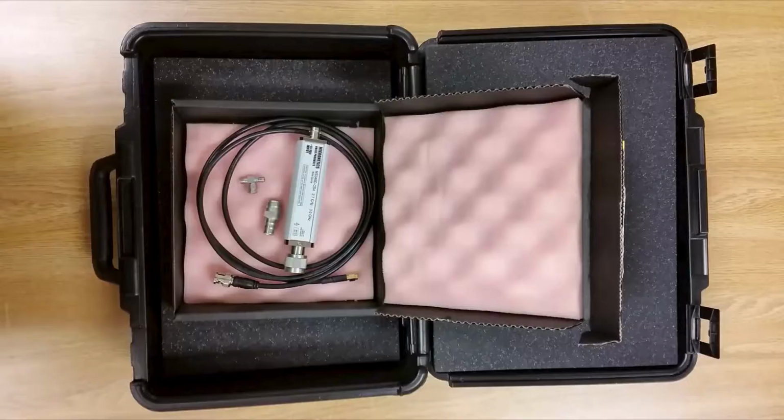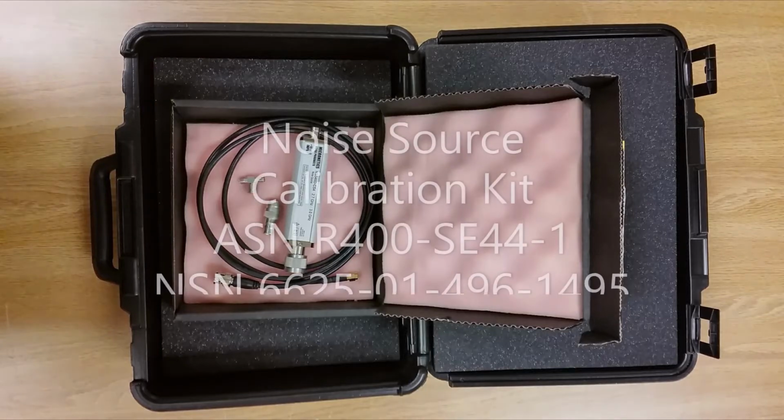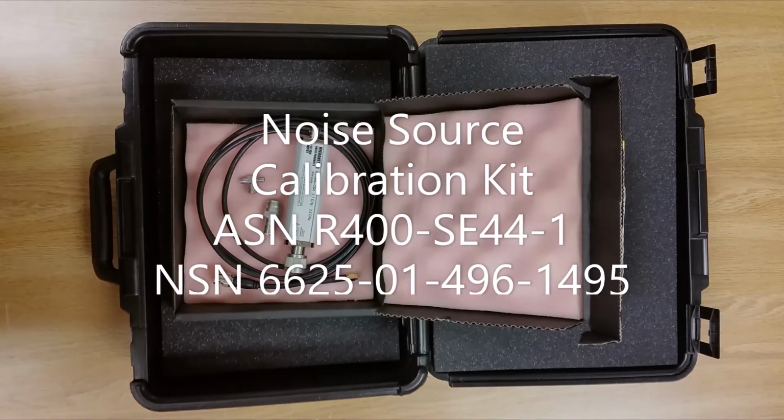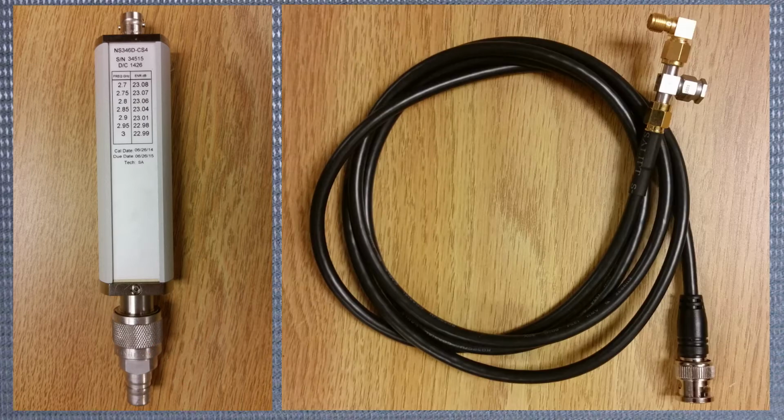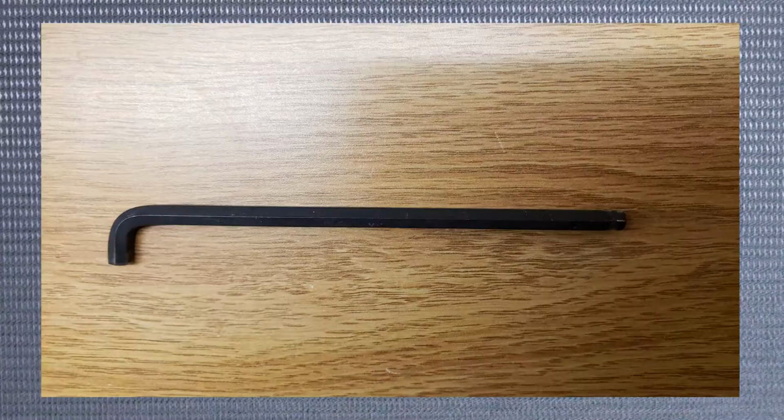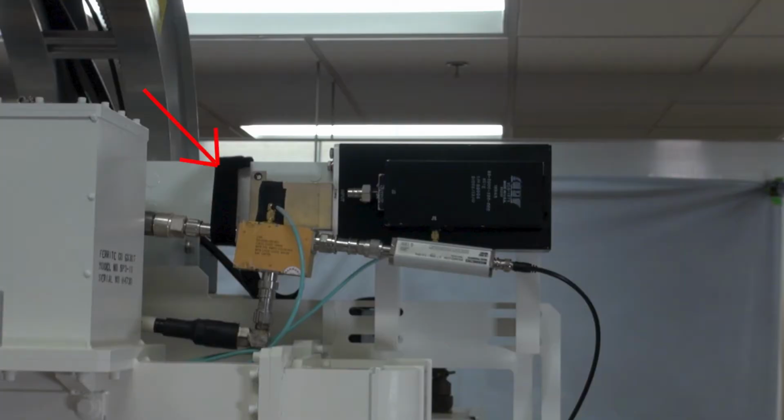This procedure requires you to pre-order from Shared Support Equipment Noise Source Calibration Kit ASN R400 SE44-1, which contains a Micronetics noise source, type N female to QN female adapter, BNC male to SMA male cable, SMAT adapter, and an SMA right angle adapter. You will also need an SMA torque wrench, 3/16 Allen wrench, and tie wraps or Velcro cable tie to secure the LNAs when disconnected from the TR limiters.